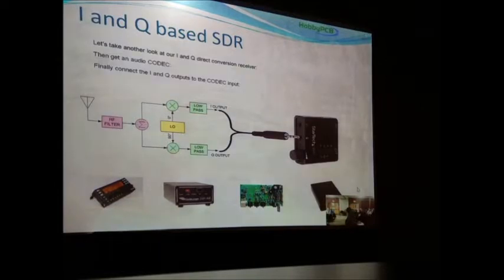Well, that's what the sound card is for. That's what the digitizer, or the StarTech in this picture, does. It takes those two signals and applies them to the left and the right audio signals, and that's where the digitizing happens. Okay, I see in the picture now that one other analog connector is a microphone, the other's a headphone, so that's not used in this implementation.